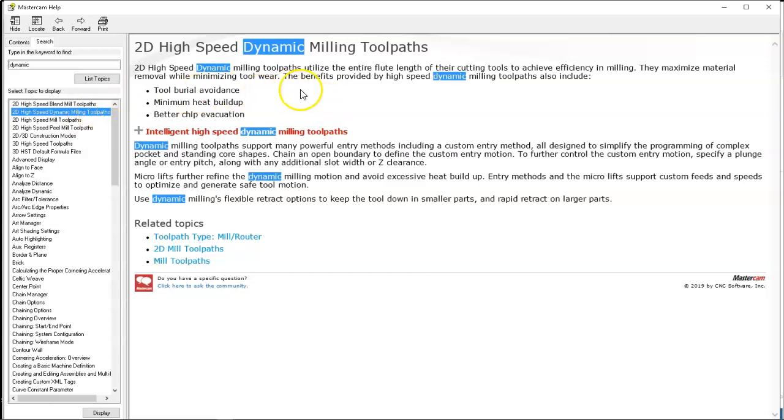So they use the standard terminology, using more of the flute, so you're not wearing just the last quarter inch. And it's pretty apparent when you have something like a titanium nitride or zirconium nitride coating, and you do a lot of pocketing at a quarter inch depth and then feed down the next level quarter inch depth, that you're putting that wear. It may only be tenths of a thousandth or over time, relate to a thousandth, but the rest of the flute really wasn't in use.